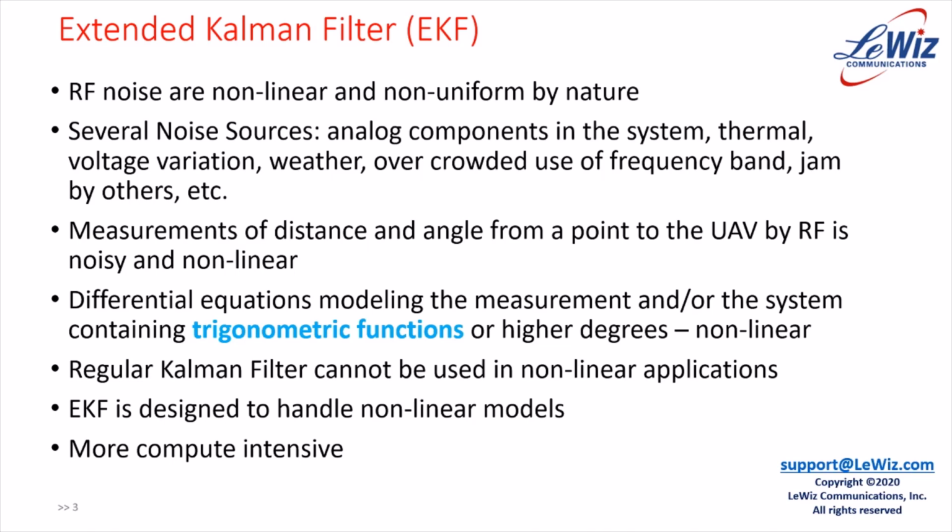Extended Kalman Filter is useful for nonlinear systems, and RF noise by nature are nonlinear and non-uniform. And noise sources can come from several things. Analog components used in the system can also have noise, and variation in thermal or voltage can create noise in the RF system.